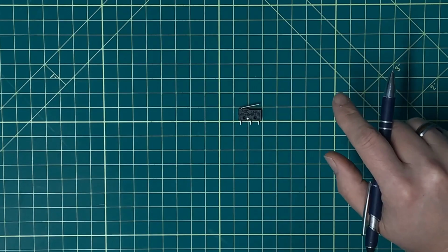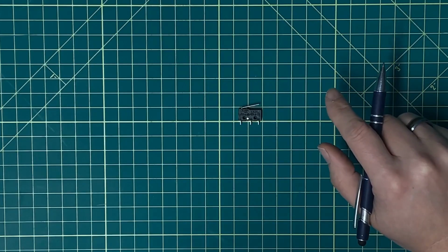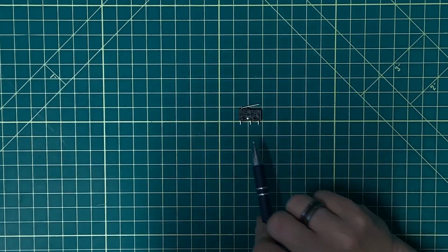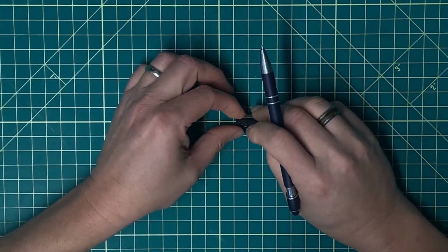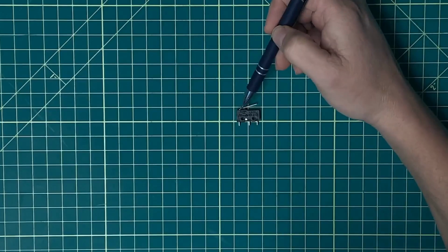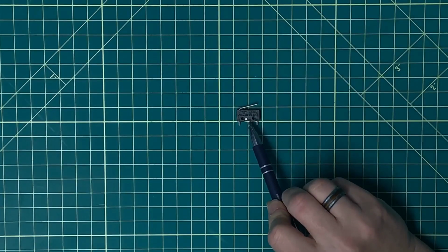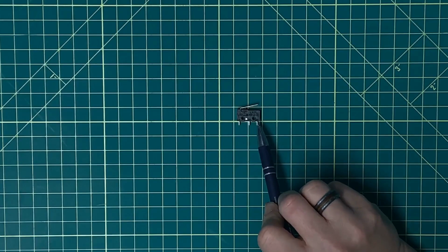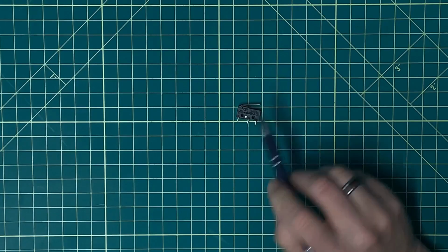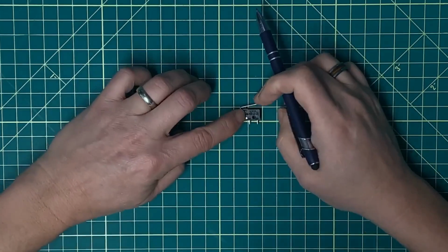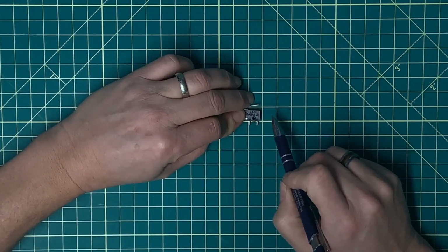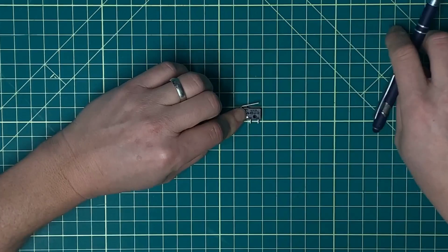What I need to switch to is a single pole double throw switch. So I've got a normally open position, and I believe this is the normally open here in the middle. Yes, a normally open position, so that in this position, this contact compared to common is open. It doesn't conduct electricity. But I've also got a normally closed pin, so that in this position, these two are conducting electricity. And so when I push the button down, these two pins will conduct, these two will not, and then release.